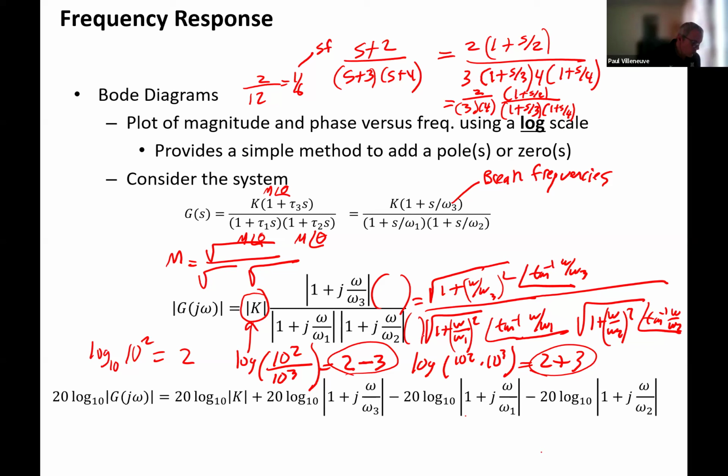And we normally use the 20 log 10, we could use the log 10, but we use the 20 log 10 because it's based on the concept of a decibel, which is a power calculation. It's based on looking at voltages, but we typically use the 20 log 10 for power conversion. It just makes it easier because our break frequencies are usually called our half power frequencies. So instead of using just the log base 10, we do 20 log 10, and then we get our results.